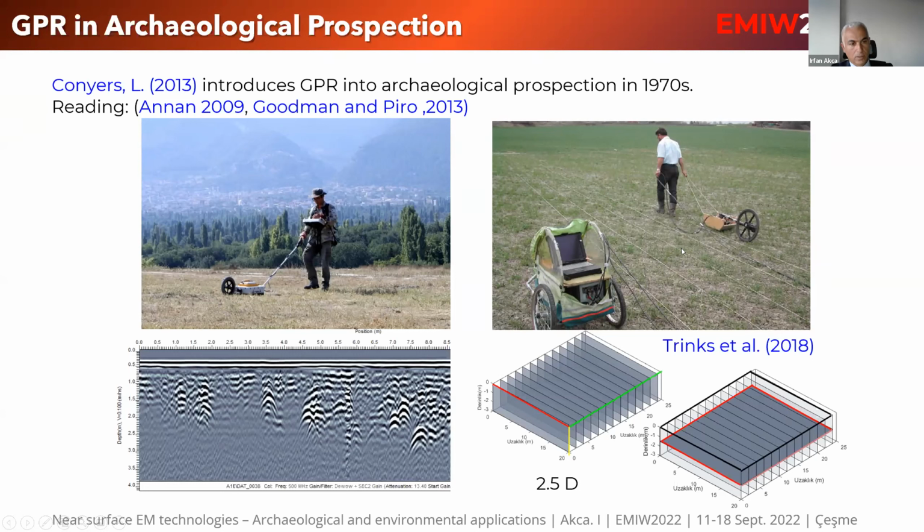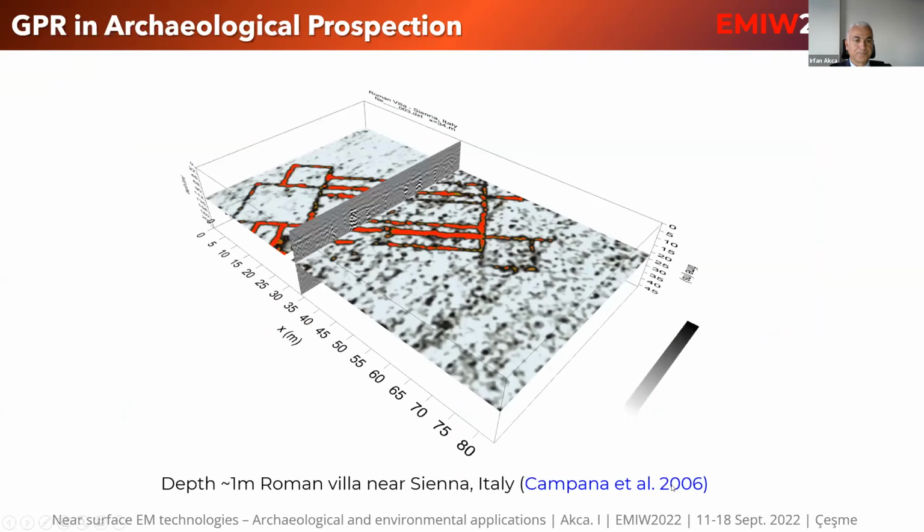If you continue measurements with a spacing in the other direction, then you can produce a depth map or a depth slice or a time slice, because we record the radar signals in the time domain. So it may be a way to measure in both directions, maybe in perpendicular directions, or in parallel to produce a model like shown on the bottom right.